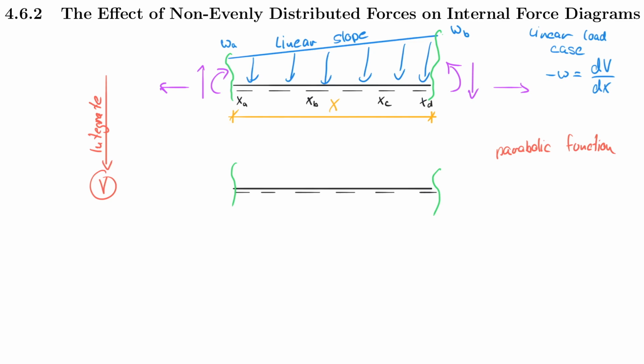And maybe to better communicate that, let's change this up here to WD now, so that we understand that that relates to each other. But what I can do now is I can say that this value here relates to the slope of the shear force function. And so I have a small value there, and don't be fooled, it looks like it's positive, right, because we are above the dashed line, but keep this negative in mind. So sometimes when people see this negative, they just want to draw a negative function here, but it's the slope that is negative.